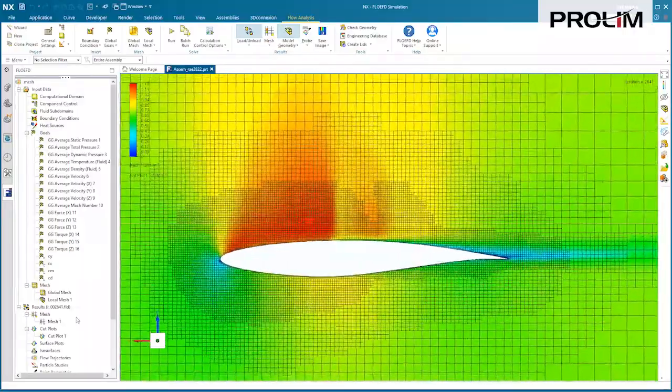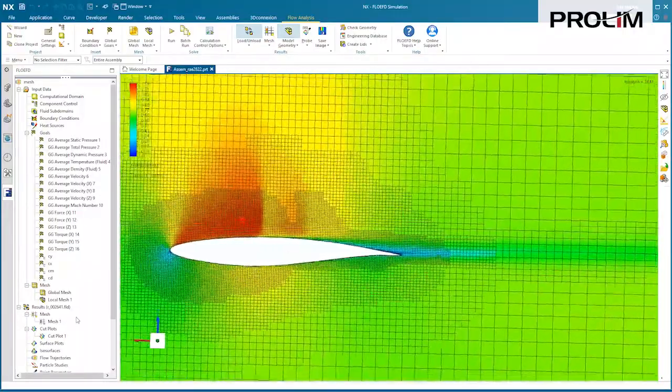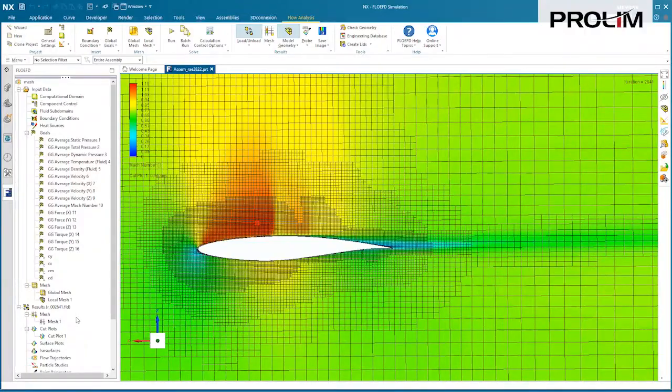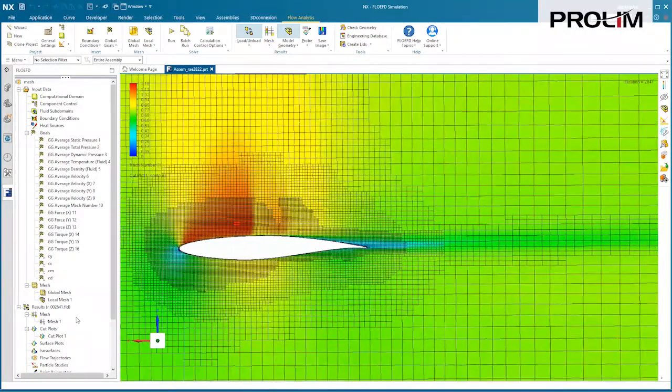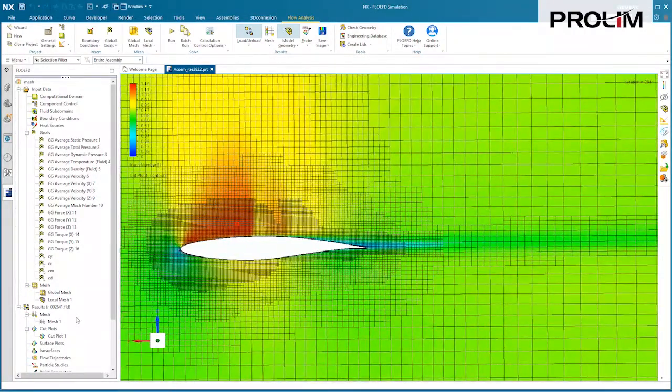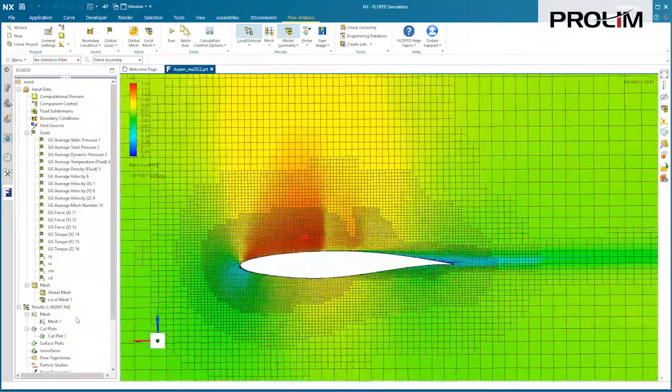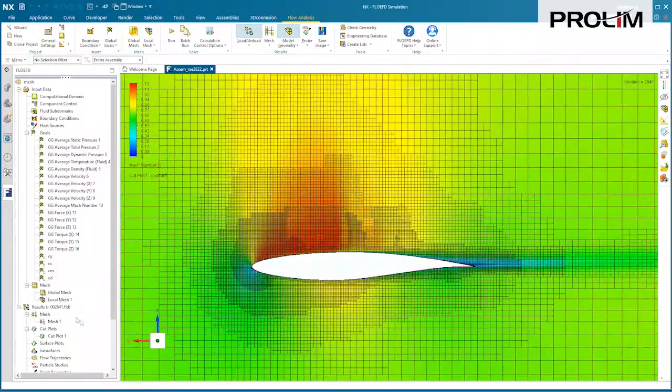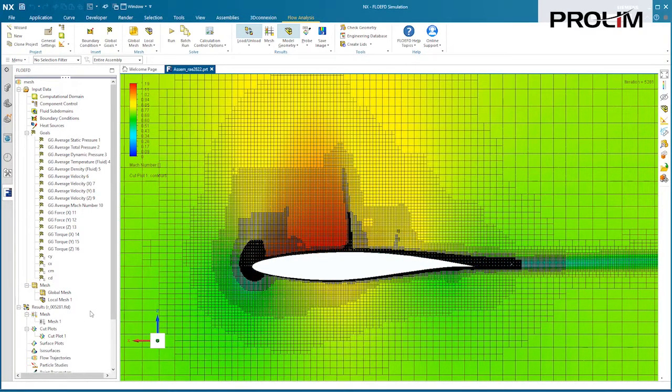We can now see a spread of refined grid cells created by the solution-adaptive mesh refinement based on flow gradients. The mesh refinement also occurs in the wake zone behind the wing to capture these flow gradients in higher resolution. The final mesh, after several adaptive refinements, has over 300,000 grid cells. Additionally refined grid cells can now be seen at the leading and trailing edges, as well as the shockwave location. Finally, showing a cut plot of Mach number shows a nice crisp shockwave as a result of our high mesh count.